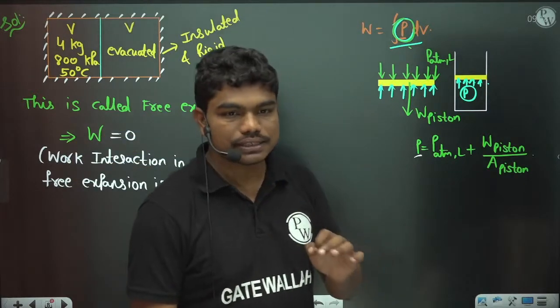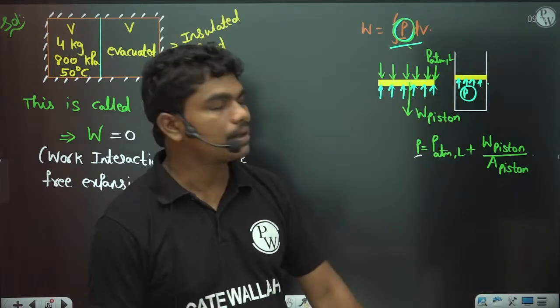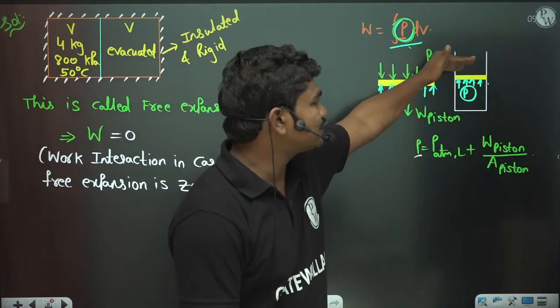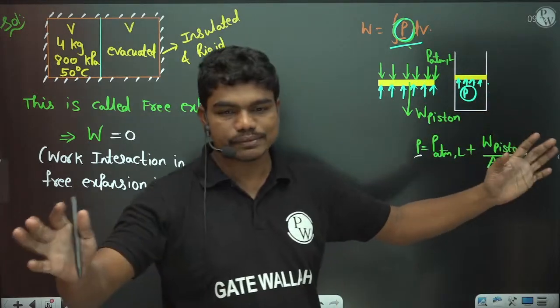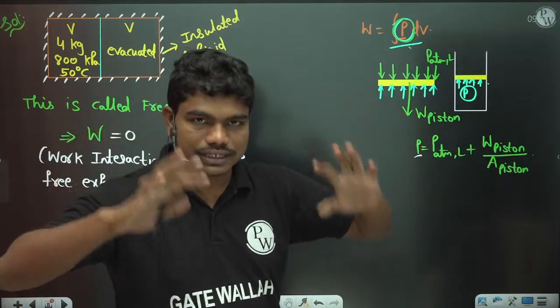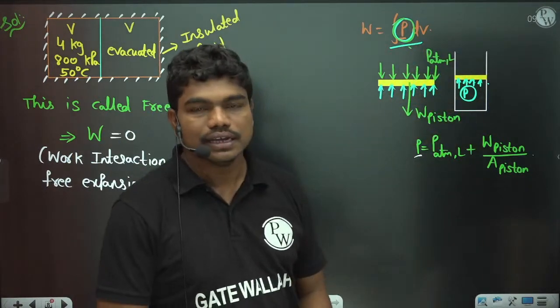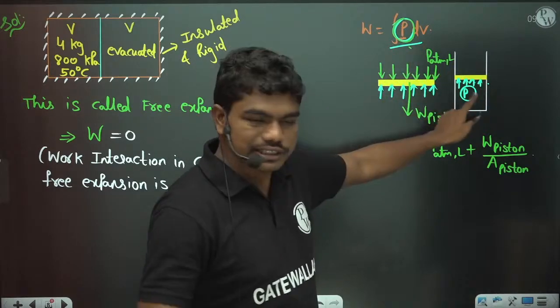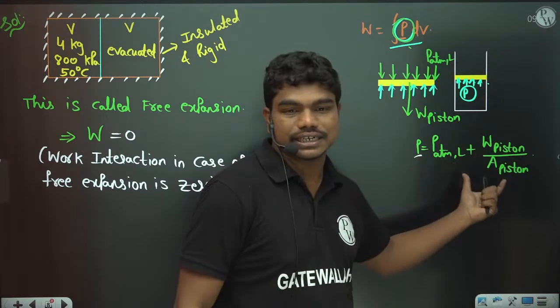So that's why, similarly, work done is always against some external resistance for the movement. In this case, whenever the piston has to move, the atmospheric pressure plus these other things all contribute some external resistance on the piston, and the gas is actually doing work on that piston. So this P that you are substituting is the pressure of the gas, of course, but that is mathematically equal to this particular resistance.